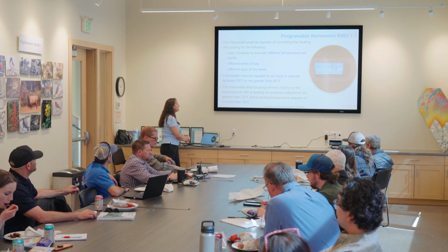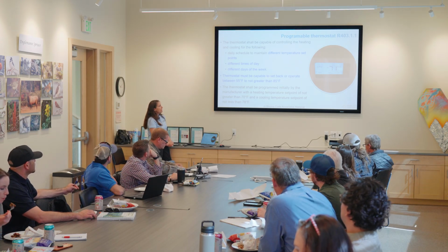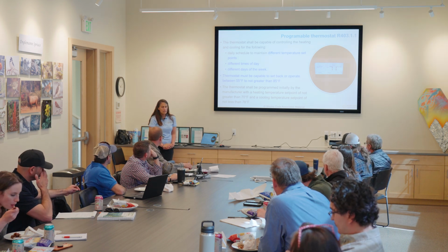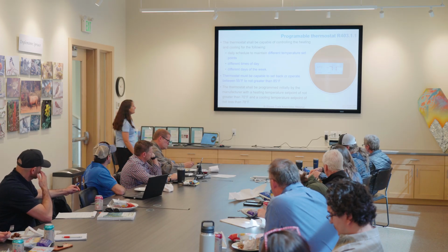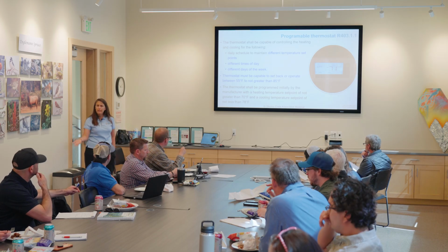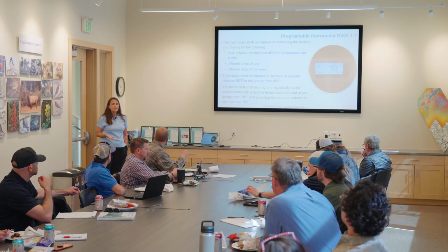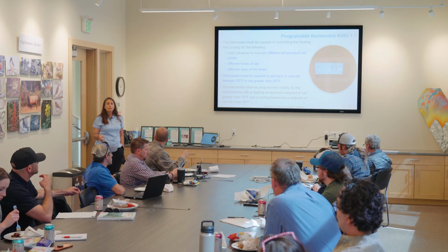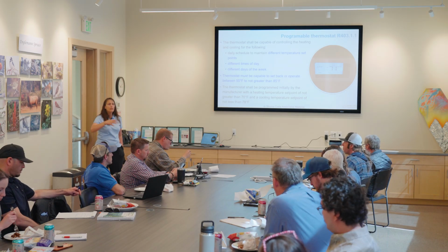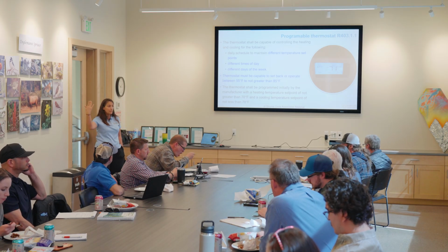Now, there are some criteria that talk about the thermostat must be capable to set back or operate between 55 degrees and not greater than 85 degrees. That's typically something that's addressed with the manufacturing, right? The manufacturers ensure that it can't, basically what they're trying to say is you can't require that the thermostat only work from 70 to 75 degrees. It has to have the ability that if the person wanted it to go all the way down to 55 or all the way up to 85, that it can do it.